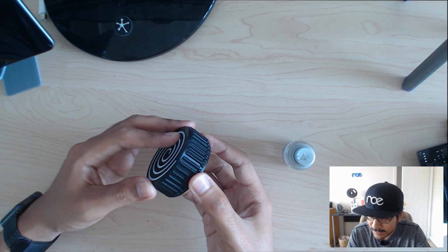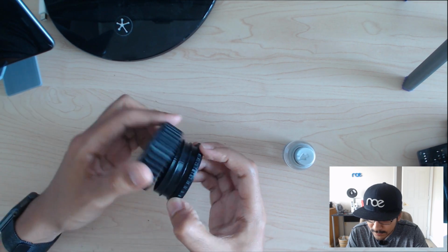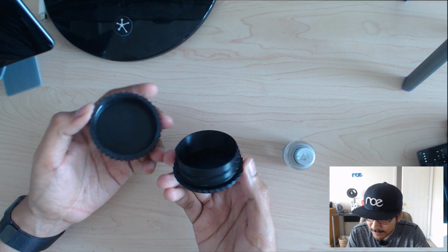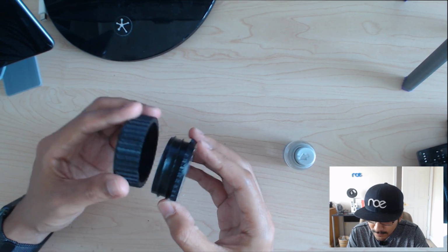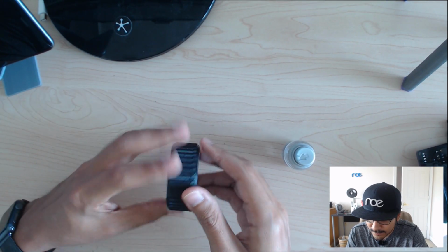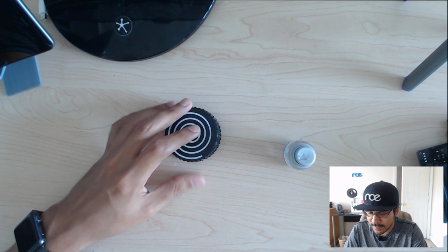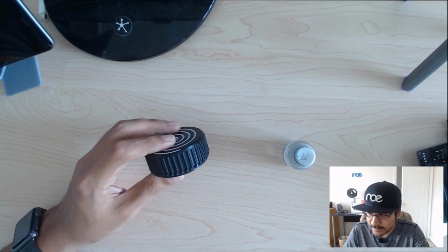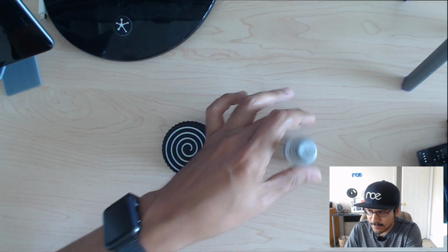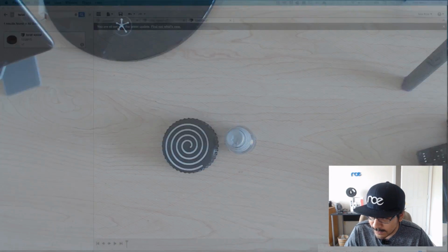This is something I made a little bit ago, which uses a coil feature in Fusion 360 to make this custom thread. You've probably seen me use the standard thread feature in Fusion 360, which makes standardized threads. So this is a good tutorial on how to make custom threads for something like this, or if you wanted to make something like a twisty top for a bottle. So let's go ahead and take a look at the CAD.